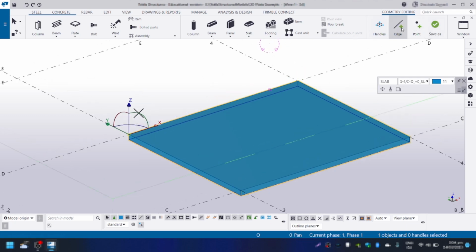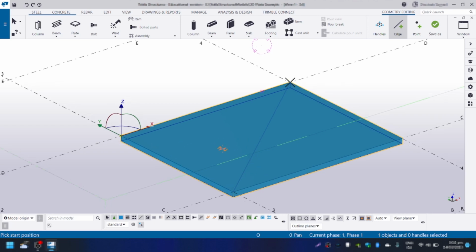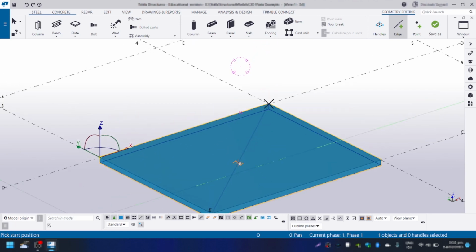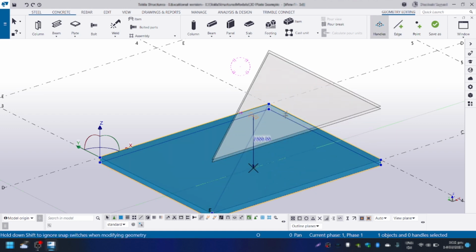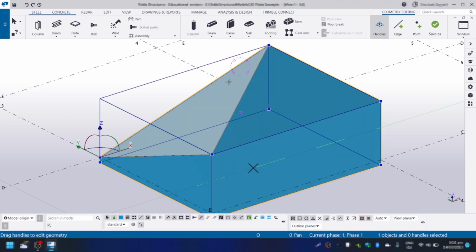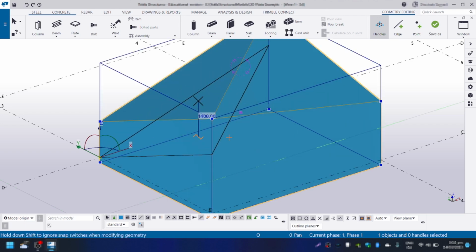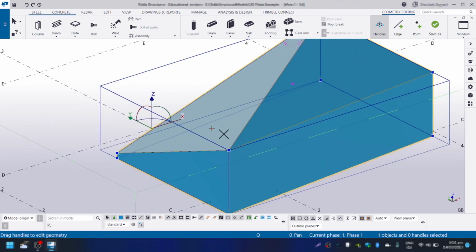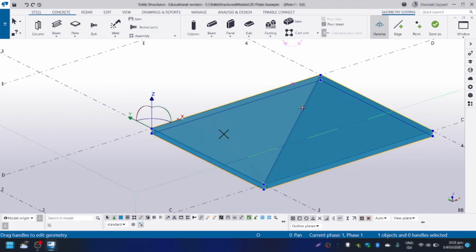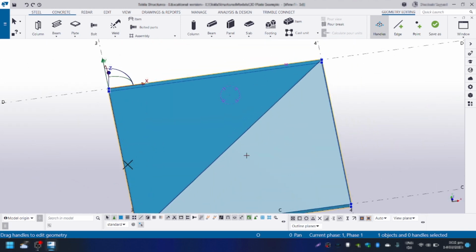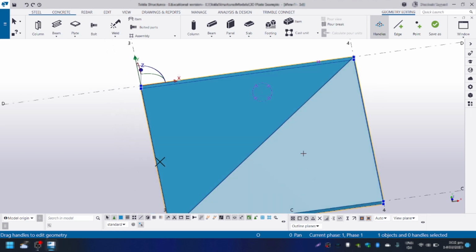So what I'll do now is click edge, and I'll draw an edge from these two. You see it's drawn this line over here. That basically is like a divider. When I click this again and I click on handles, I can now select this thing. You see its shape is changing. I can extrude this as I want. That's what adding the edge has done. It's basically divided that object's geometry into two parts.